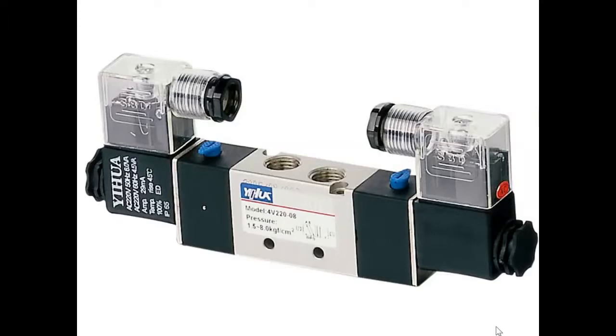This is a pneumatic valve. This is a solenoid valve. And on each end of it, you see electrical connectors. So inside the black plastic boxes that have the little knobs on the end are coils of conductor. And in between the two black boxes, going through the entire valve body, is a spool. It's basically a rod that has grooves in it, and as the two solenoids pull the rod back and forth, it connects chambers between the ports.